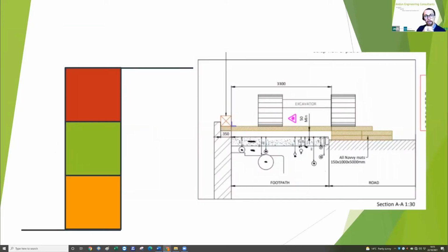Another point to note on retaining walls is that any high point loads that may be applied behind the wall from building foundations or crane loadings really need to be taken into account. Walls are generally designed for blanket surcharge, but high point loadings need to be reviewed separately, as they may well present a worse case. It's worth considering if the crane can directly load the top of the wall, as this can act as a stabilizing force.